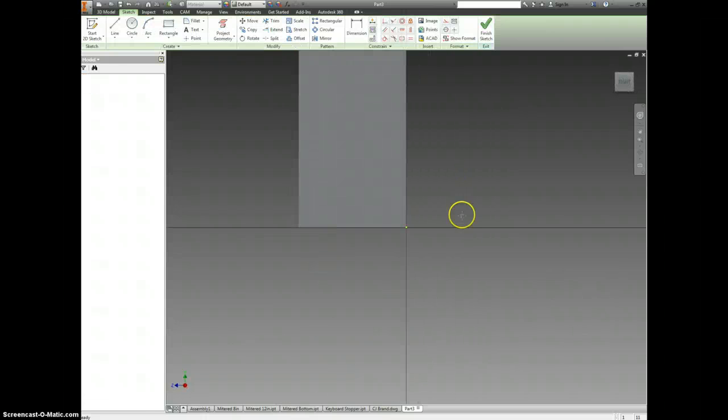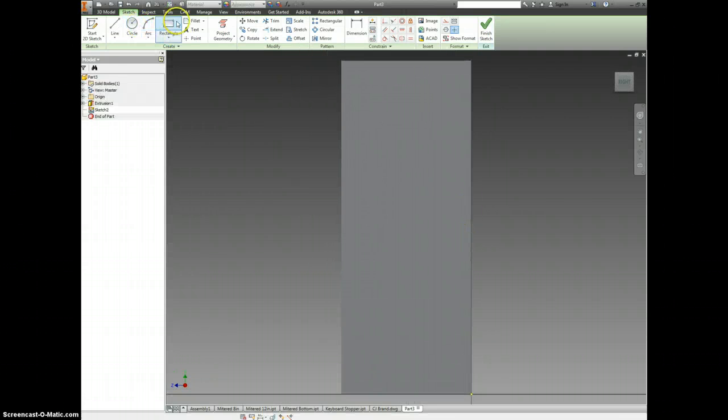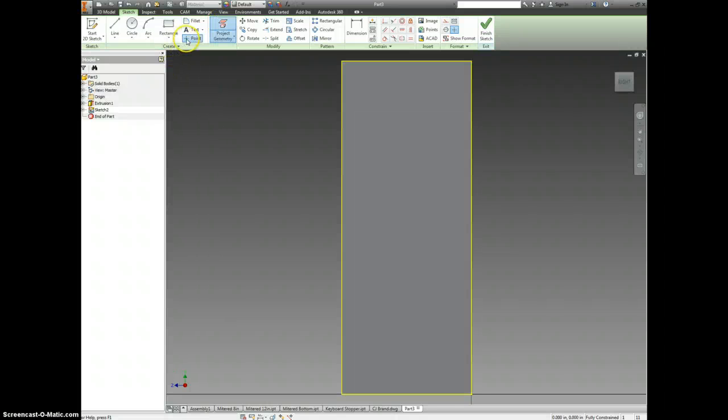I'll make a new sketch over here somewhere, and let's project the geometry and make points. There are 4 points all together. It says that the first point is located from the edge by 0.75. These are 1 inch apart, the next two are 1.25 apart, and these two are another 1.25.